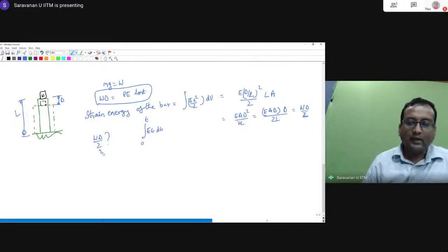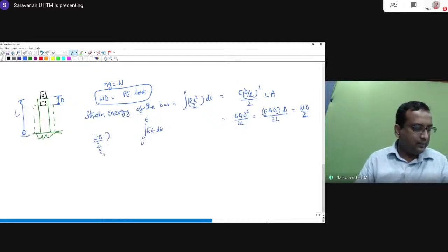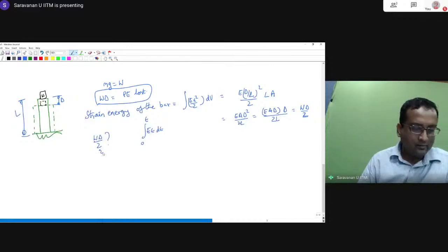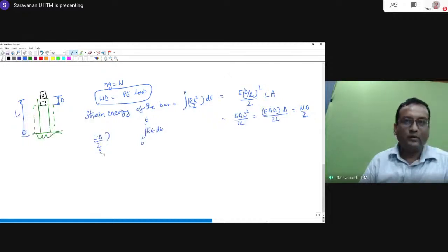See, the stress cracking due to corrosion is not dependent on the strength of the material alone. It depends upon certain other factors also. So strength of the material alone doesn't mean that you have a better chance of not cracking due to stress corrosion.